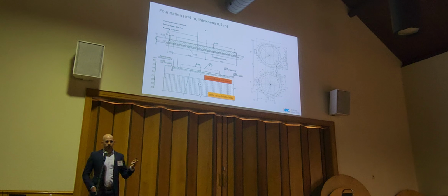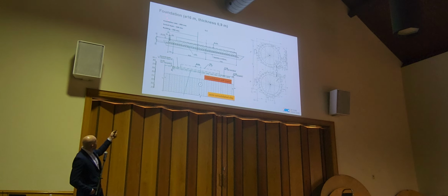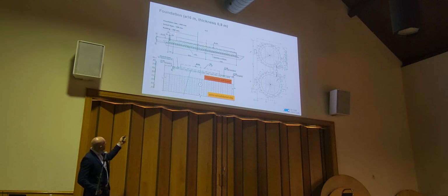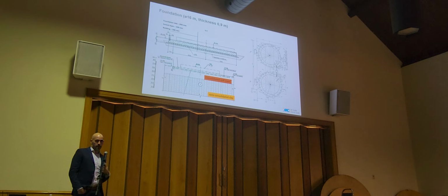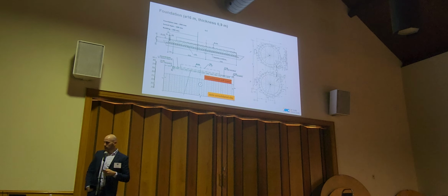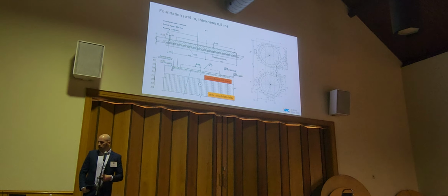So you see, you have here first of all 80 centimeters of concrete, then some screed layer of 10 centimeters, then we have a bedding of 300, and then we have consolidated stiff loam, but below we had semi-consolidated clay. By the way, so that you get an idea for the dimension, the water tank was 16 meter diameter.